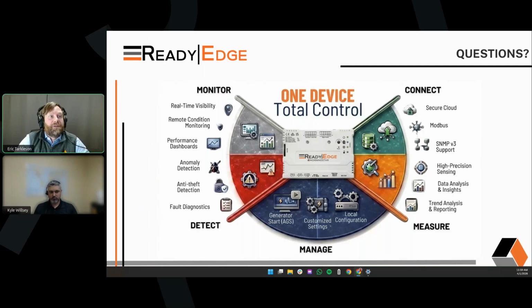So it's both hardware and software protocol. So it's an RJ11 cable like the old phones, and most of our products have them. Most of the professional series products have them, the ProStar MPPT and up. And it's around to stay for continuing to network our products together.